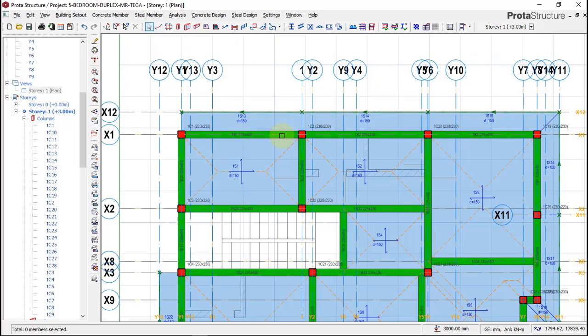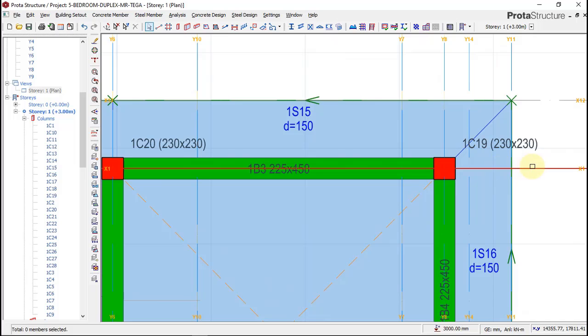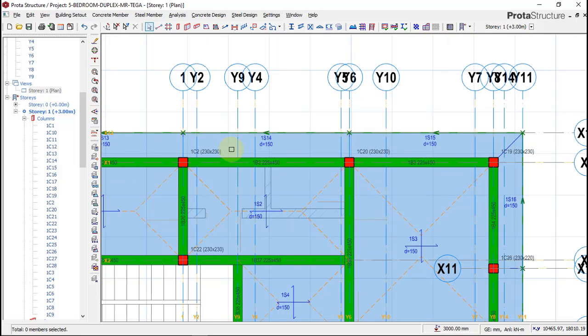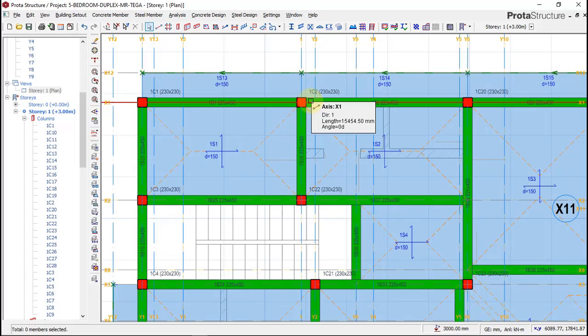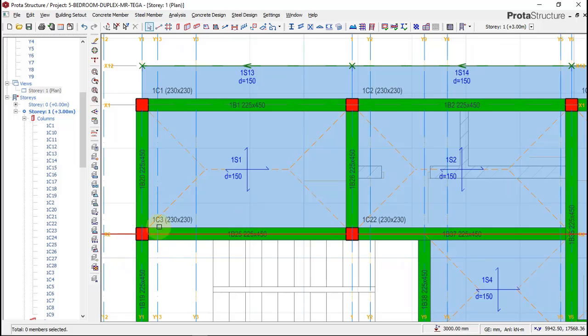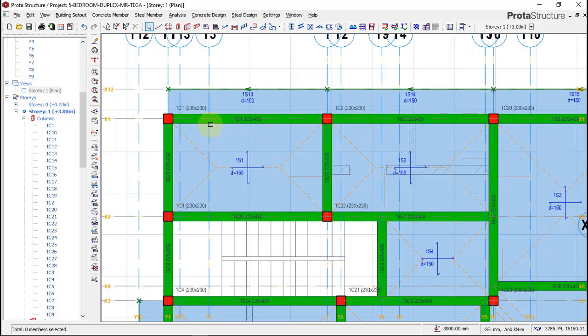This is a continuous beam. This is a continuous beam. So the moment here must be 0, and the moment at this place must be 0, because there is no beam continuing on this area. Right now, as it is, they are all fixed conditions. All the ends of the beams are fixed conditions. So I always like to introduce a hinge, knowing that moment at an end must be 0. Most people don't do this, but like I said, this is a practical base. I always like doing it.